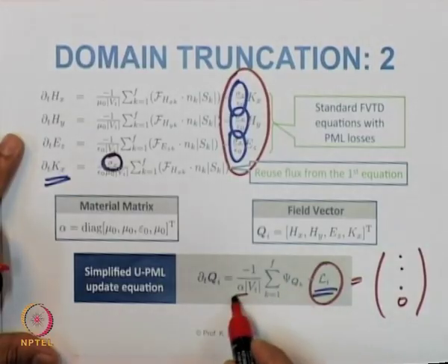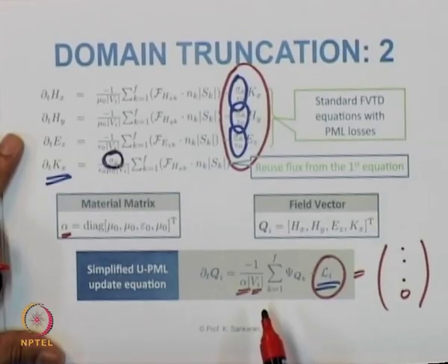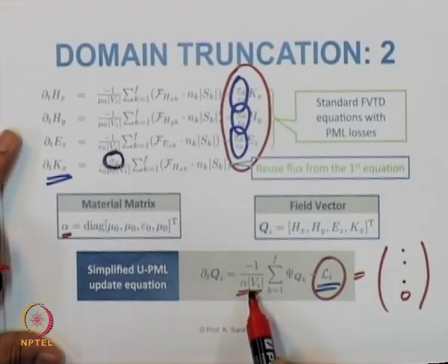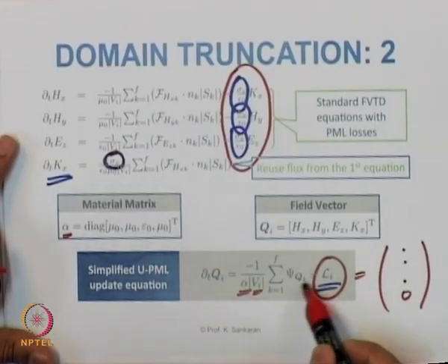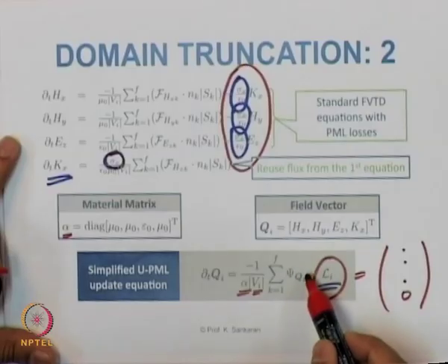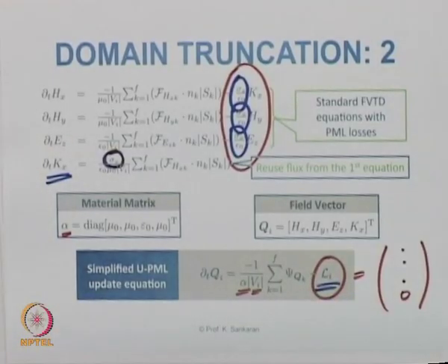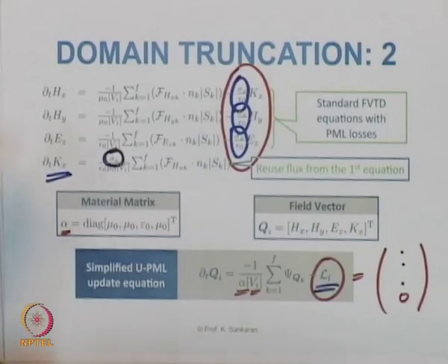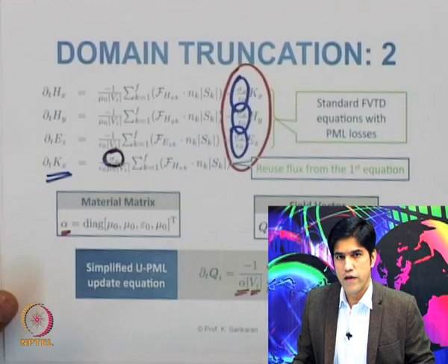And we discussed alpha, which is given here, and V_i, as we already know in the finite volume formulation, is the volume of the cell. In the case of 2 dimensions, this will be the area, and then we will have the counterpart of the surface in the 2D case, with the length of the edges sitting here. So with this equation, we understand that this is good enough for us to model plane waves, or also waveguide truncation.